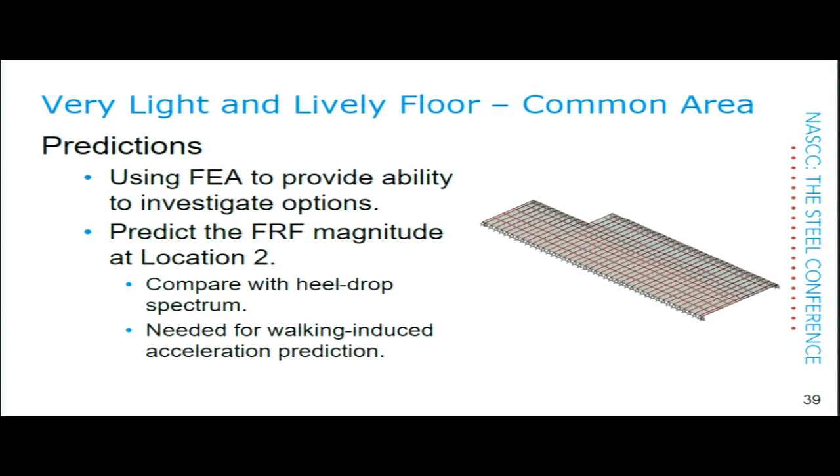Okay, so first step, we want to predict the FRF magnitude for location 2 for our discussion here today, because we want to compare that with the heel drop spectrum. They should be about the same shape. And also, we need the FRF magnitude to predict the walking-induced acceleration.